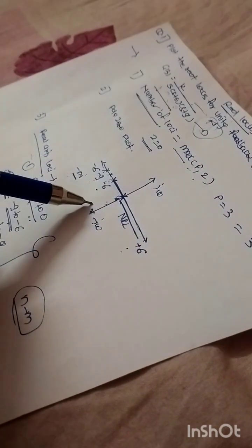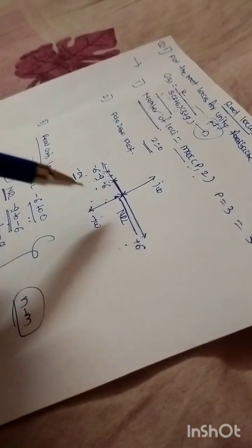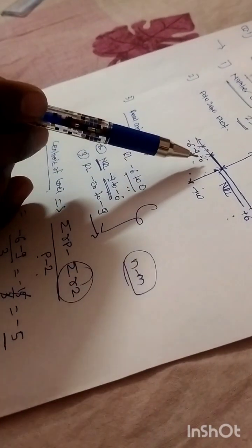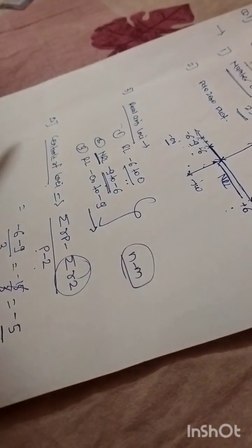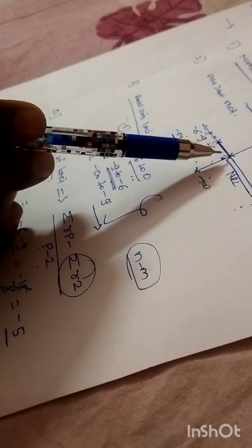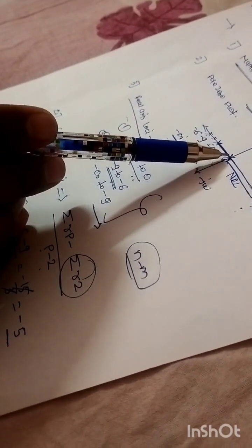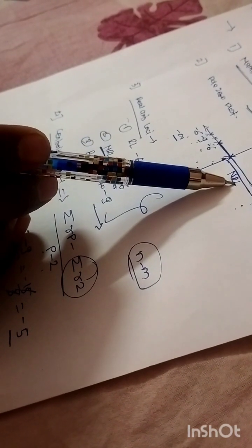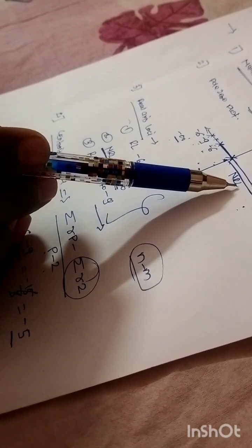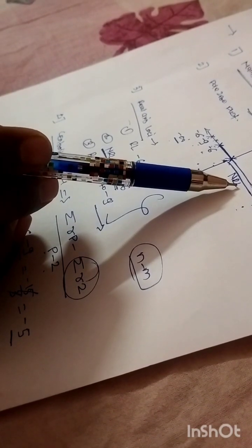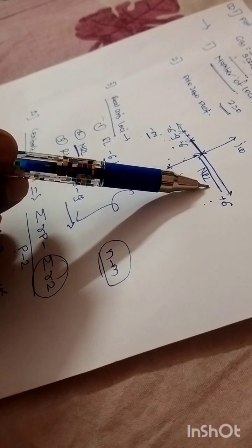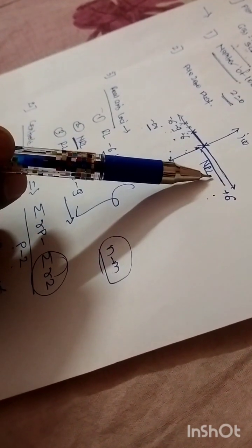This is the pole zero plot. Step number 2 is concerned with that. Step number 3, real axis loci, which is to be tabulated from this pole zero plot, right? The simple logic for this is, when we consider the first pole, to the right hand side of this first pole, if the number of zeros plus number of poles is an odd count, we can say that there will be a presence of root locus.